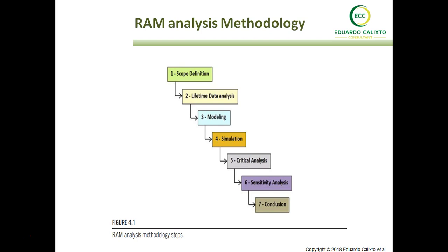On the other hand, if you have a FRACA system where you've got the basic information from the FMEA, such as failure modes, detection, consequence. So if you have clearly the failure modes, you can carry out lifetime data analysis at the failure mode level, and then you can also organize your RBD at the failure mode level.